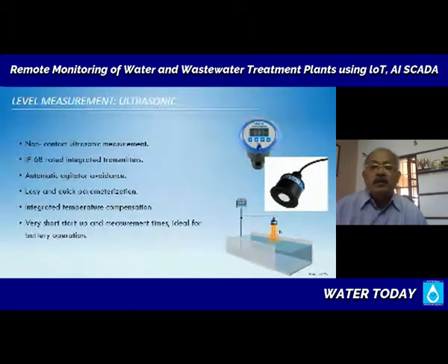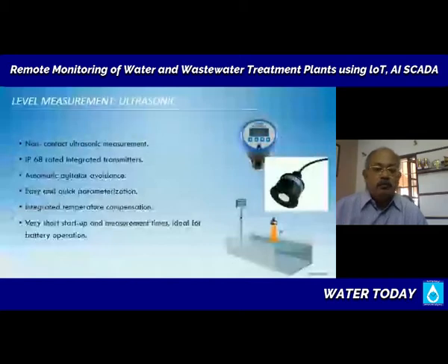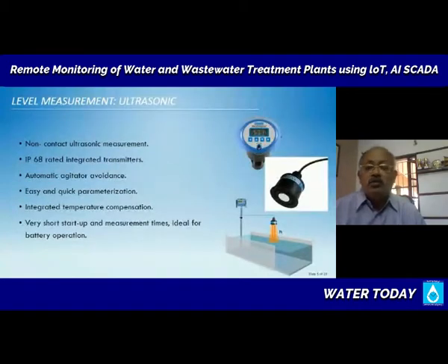Well, what happens if there is an emergency, your pipeline has broken, and you don't get any supply for a few days? You will be depending on water stored in the tank to keep supplying water to the users. So it is important that you maintain sufficiently high levels of water in the storage tank at all times. And this also is important in terms of safety, in many cases where you need water for firefighting and some such issues. It's important that you maintain the water level in your tank.